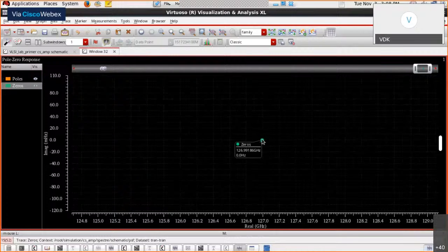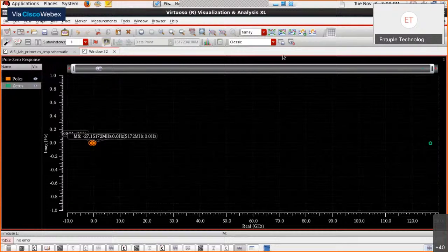All right. So that is the illustration of the GM over ID technique for two simple circuits. One actually is the simple common source amplifier with the NMOS device as the active device with a resistive load for a design set of specifications which focus on the desired gain, the small signal DC gain, right? And then the same circuit modified to get a common source amplifier with one more transistor, the PMOS device actually as the current source load. Having done this, let us next move over to the design of a complete two-stage op-amp at the schematic level, right, using the GM over ID technique.